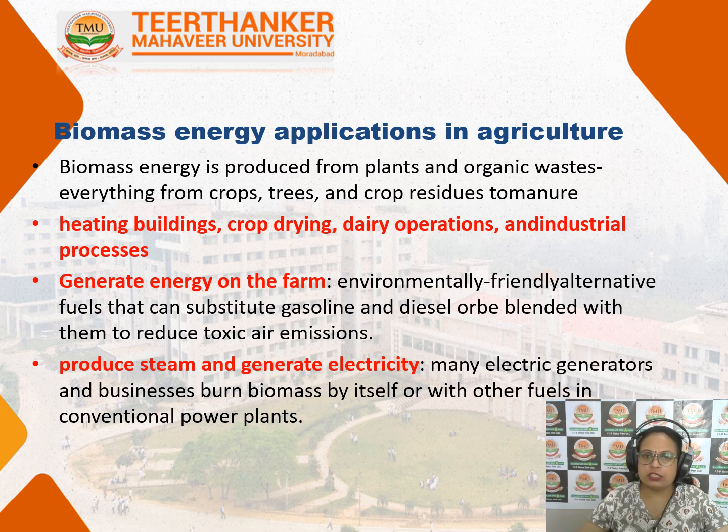Next important energy is the biomass energy. Biomass is actually the agriculture material and agriculture leftover that remains in the fields, which is of no use. Now this no-use biomass can be used for various purposes. Briquetting can be done. These briquettes can be utilized for heating purposes in the industries, in different daily operations. Crop drying can be done with the help of the heat produced from this crop produce.